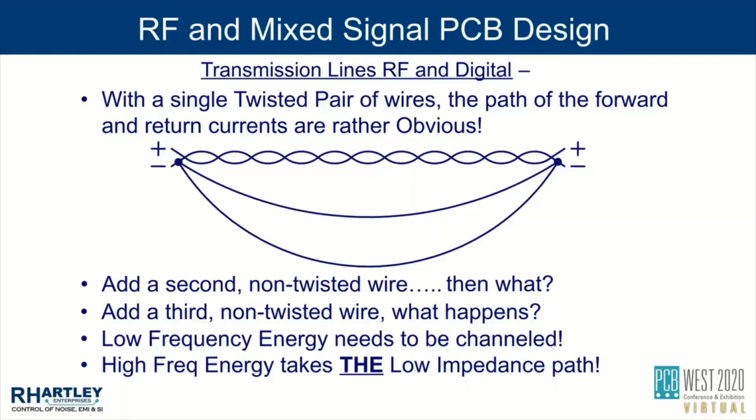That would start to diminish. And this would continue on until you reached a few kilohertz. And again, by 5, at most 10 kilohertz, all of the energy would be traveling in the twisted wire pair, and there would be absolutely no field coupling to the other two wires hanging off of the negative wire. Hence, there would be zero electron movement in those two wires.